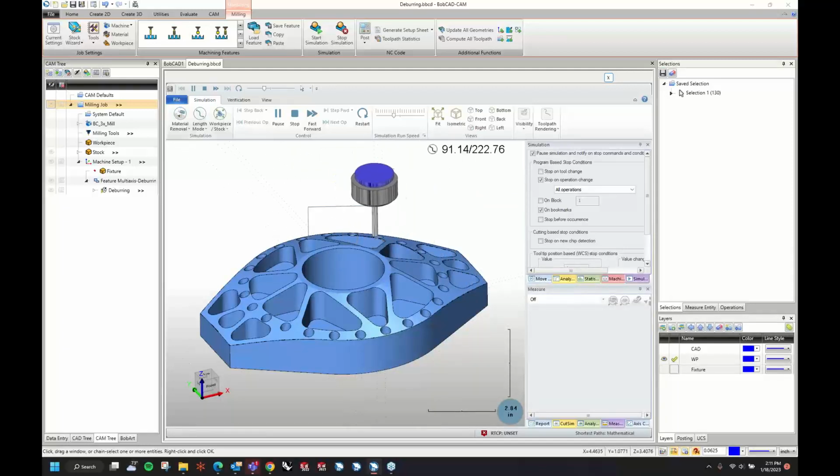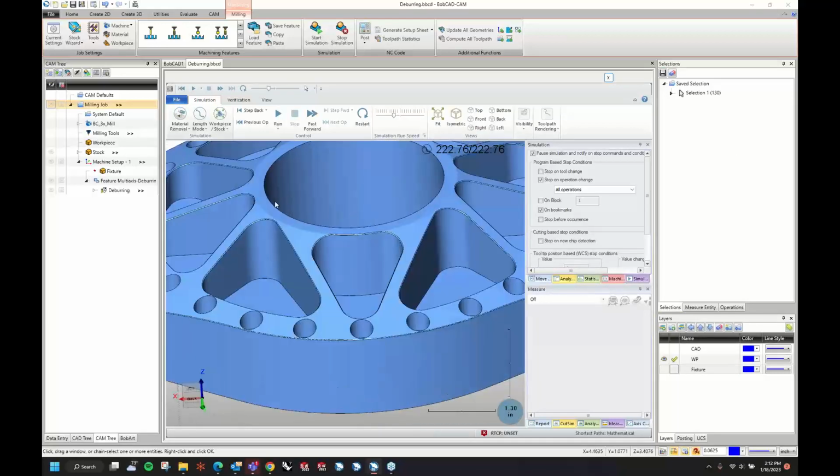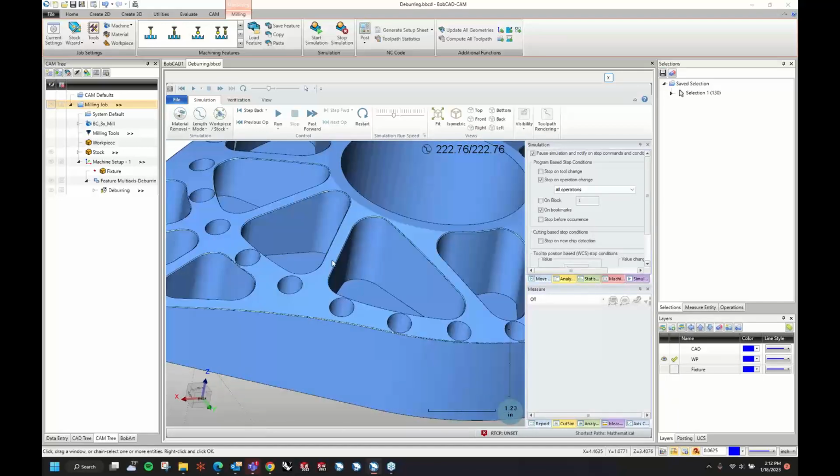And like I said, again, if you guys are on version 34 and you're trying to use deburr, you cannot use a chamfer mill. That is only for version 35. Yeah, the only thing else that I might want to add to this is maybe that inner circle, but all of that looks pretty decent.